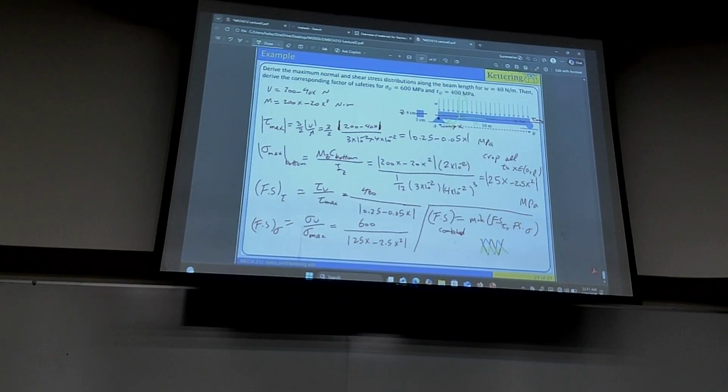But the thing that you said, you calculated one value. But this in terms of x is for the entire length. Where is the maximum? For one of them, it could be in the middle. For the other one, could be really at the two ends. So you plot it so as to see the entire profile. You would give me the entire thing, not just for one value. Okay, I didn't know. When you graph it, then you just point to that location. The max along the length is happening here. You're basically plotting the max of max at every location. Oh, okay. That makes sense.